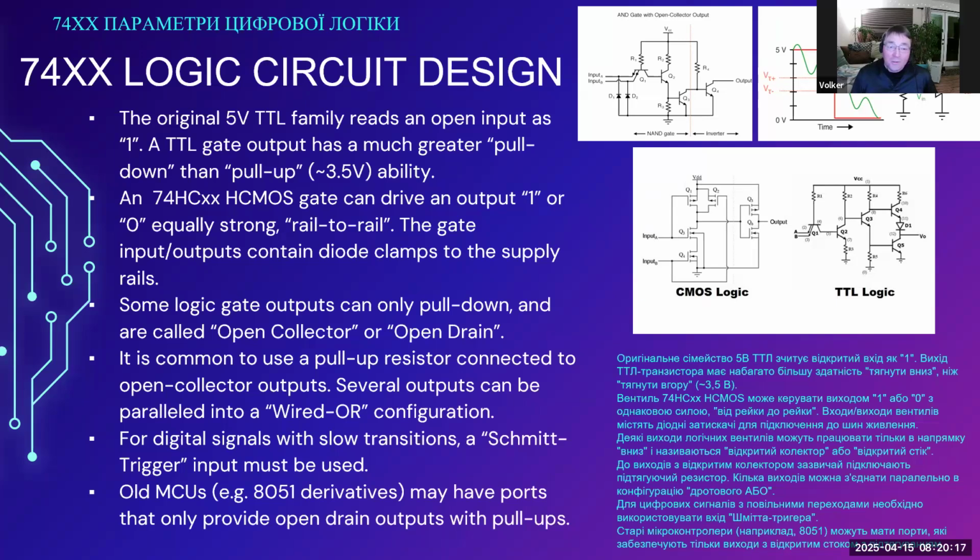Yeah, so the concept basically that I wanted to mention is that open collector, open drain, which is essentially just a transistor or a MOSFET that can pull to ground without having the equivalent MOSFET or transistor that can pull to high, to VCC. The idea that pull-up resistors are much more common than pull-down resistors. And the third concept is the Schmitt trigger.